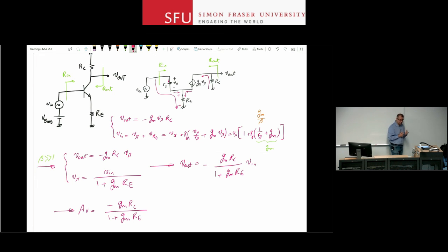So you traded off gain for some bias stability, okay? This is a very common trade in electronic circuit design. You usually trade gain for bandwidth, gain for noise, gain for input resistance. Gain is the currency in amplifier design, right? So you design a high gain amplifier, and then if you see that you're not meeting some performance aspects, usually you trade some of that gain and improve the performance parameter that you're interested in.